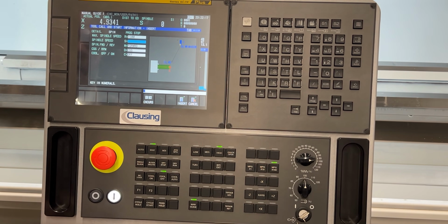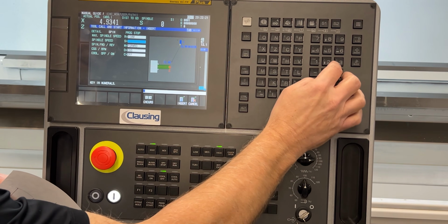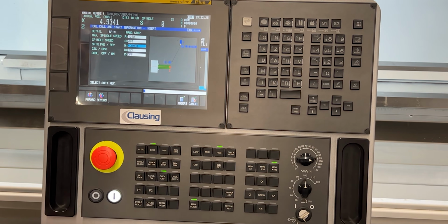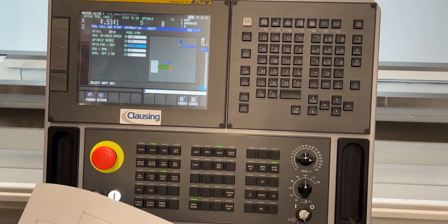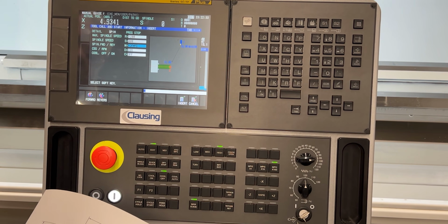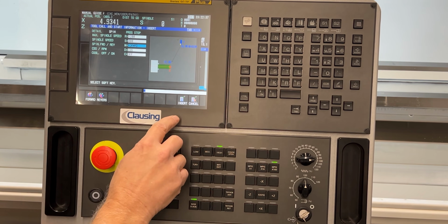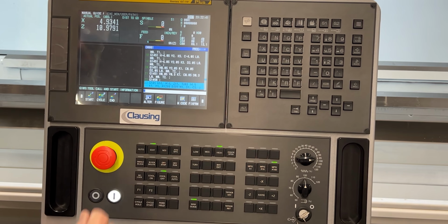Because I'm running CSS, I'm going to put in, let's say, 400 surface feet. Being a grooving tool, it's a softer insert, we can't really run it much faster than that. I'm going to have it in the forward direction. CSS is active and coolant off at this time. Then I press insert to put that into the part program.